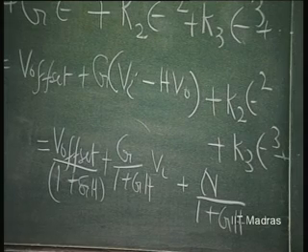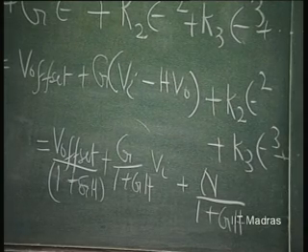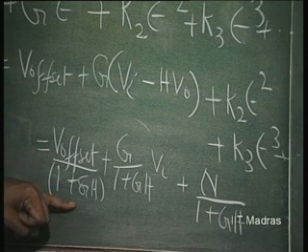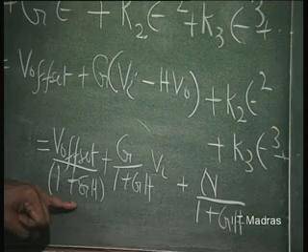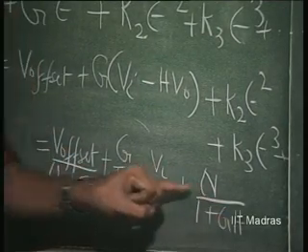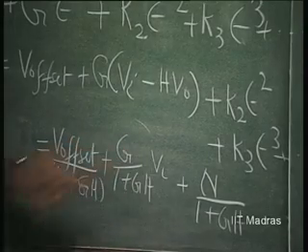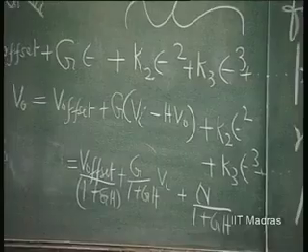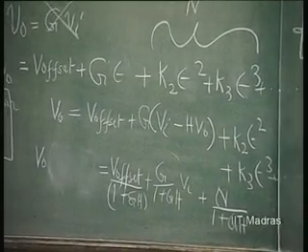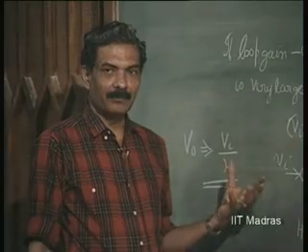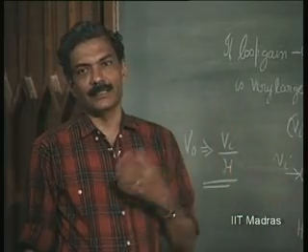So, this establishes very clearly that in any negative feedback system, the offset voltage is reduced after negative feedback, goes towards 0, and the nonlinearity is also reduced. The system becomes more linear. Now, this is an important aspect, again, of amplifier design. So, it can now handle larger signal level at the input before distortion can set in.